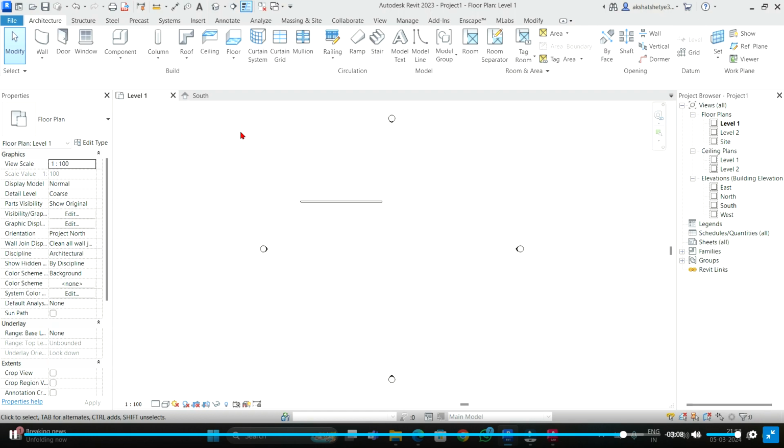As I said, as you develop, as you explore, it would be interesting for you. You can create and document any element. Let's say you have a door for a project, and that's the door which you want to create because you don't have that specific family, you can create it according to the requirement. So that's how detailed you can go as well. Clear? So this is one thing we need to keep in mind while we are working over Revit.